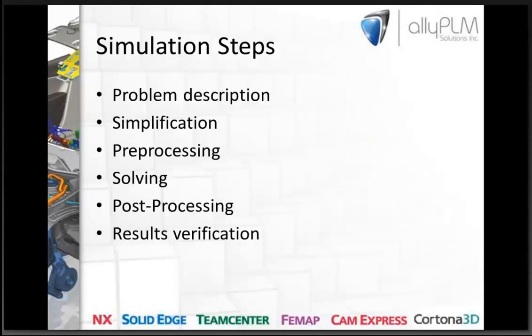In all simulation, you'll have problem description, which is very important, simplification, which is also very important, pre-processing, solving, post-processing, and results verification. And all those steps are critical in any FEA analysis that you're going to do.